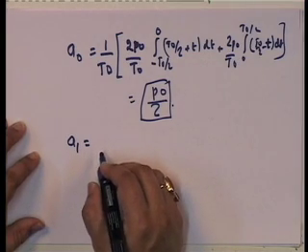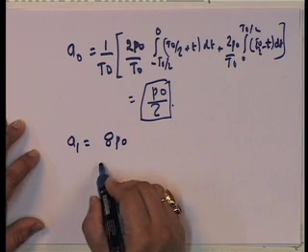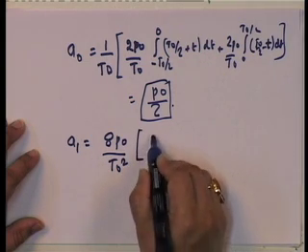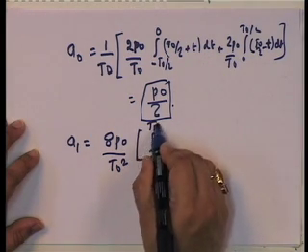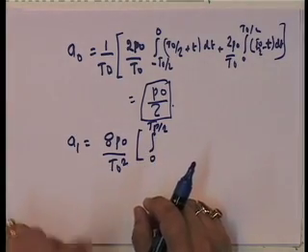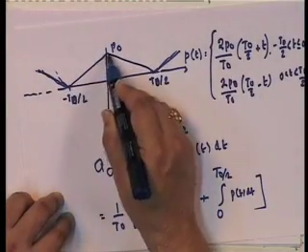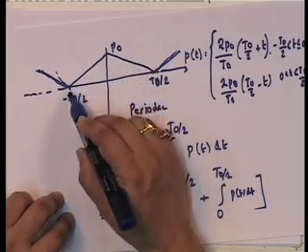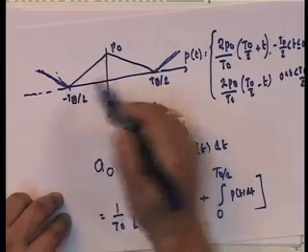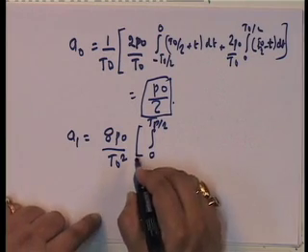And so, this is going to be equal to 8 P naught upon T 0 squared, 0 to T naught by 2, because note that this is an even function, cosine is an even function. So, when you have an even function and an even function, what happens? You can just do this into this, and this becomes just twice of that. So, that is what I have done. I have just taken one of them and just done twice the other.